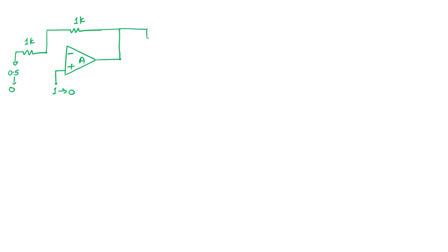If I want to see the output calculation, then what will we do? Simply apply a test voltage source and observe the test current. And simply, what is R out? R out for the closed loop system will be dVt by dIt. Okay. So offset is not an intentional voltage.